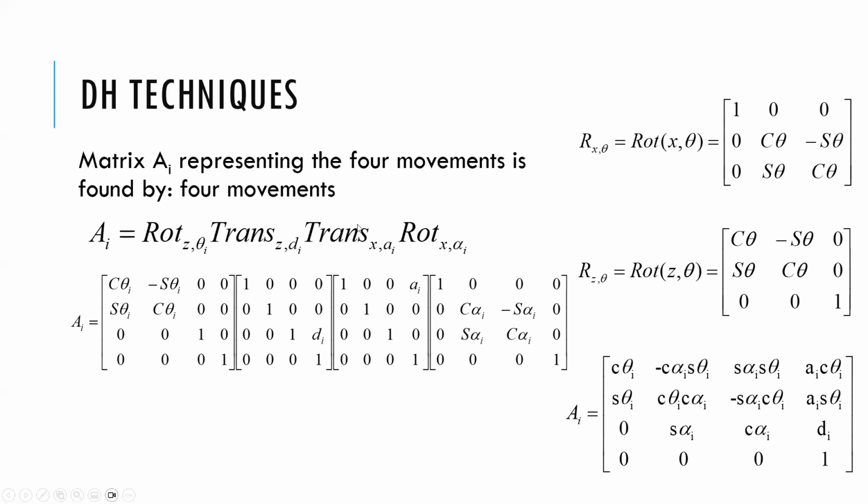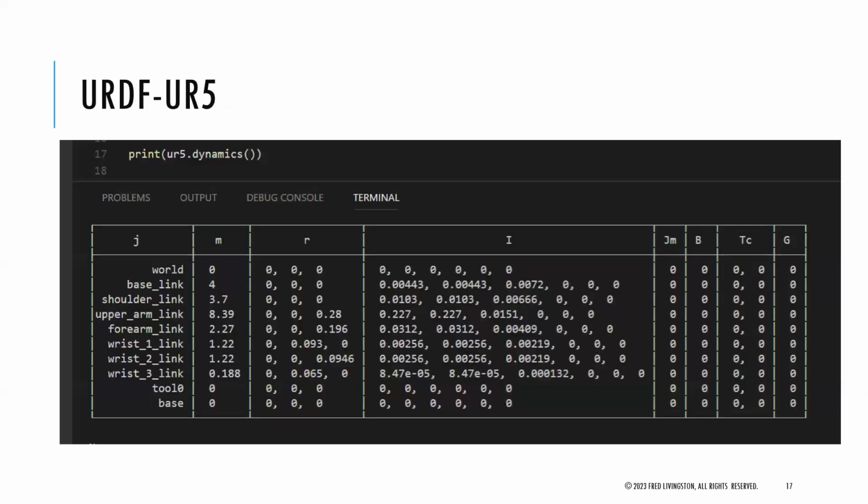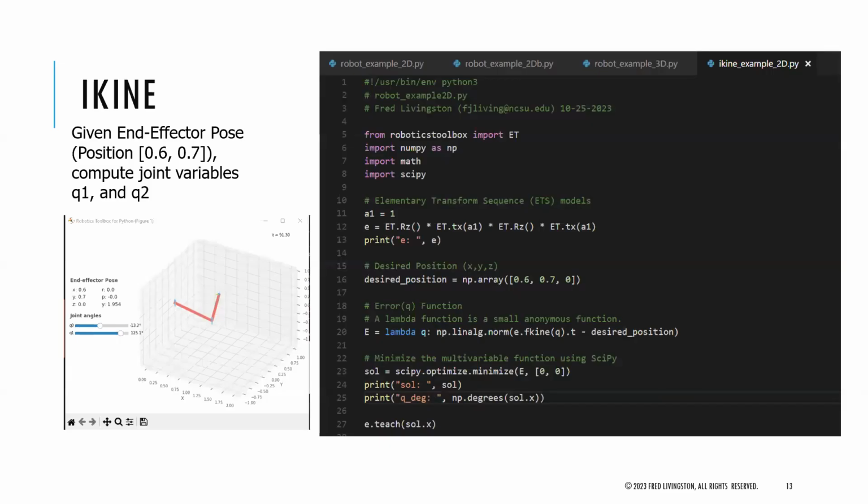Yeah. For all the rotation and translation, do they only move in one axis? For example, rotation, I think it's only for Z. Is that correct? Yeah, sure. Your rotation is only about Z. That's correct. And so you only use Z and X axis in the DH convention there. And in my other convention, I could use the rotation in Y to get to certain things here.